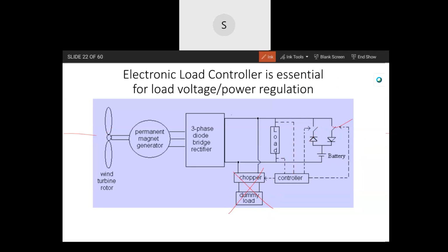So power is taken from the wind, and the generator is not able to transfer it to any load. There is no sink. The only possibility is that the turbine will accelerate, storing kinetic energy. That's the only way it can store it if it is not delivered. So it will do that, but how long? Till the first blade flies away.